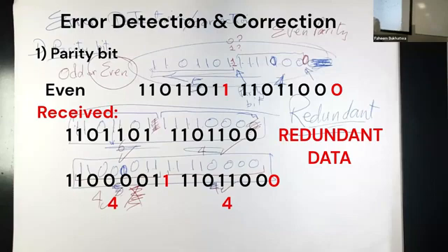1 in 8. So every time you send 8 kilobytes, in fact, 1 kilobyte of it is not user information, it's redundant information. If you're sending 7 million bytes of user data, you have to append to it 1 million bytes. So it's a ratio of 1 in 8 or 1 to 7. That's a lot of weight by all standards. So we look at other error detection systems that don't send that much. This is almost 10% of the transmission you make is redundant information. It's not really user data. So automatically you're losing 10% of your transmission, wasting it on redundant information.